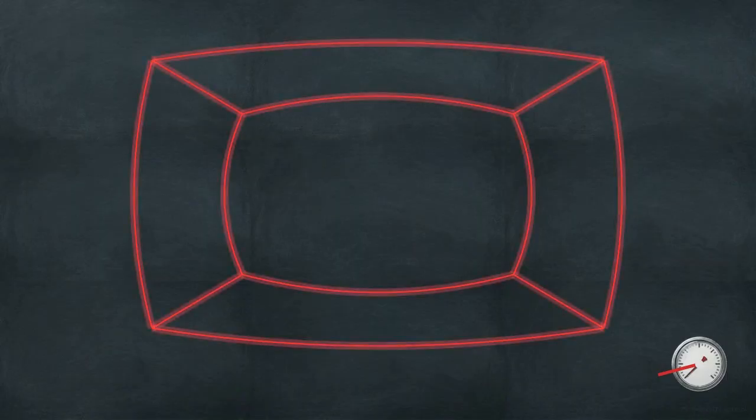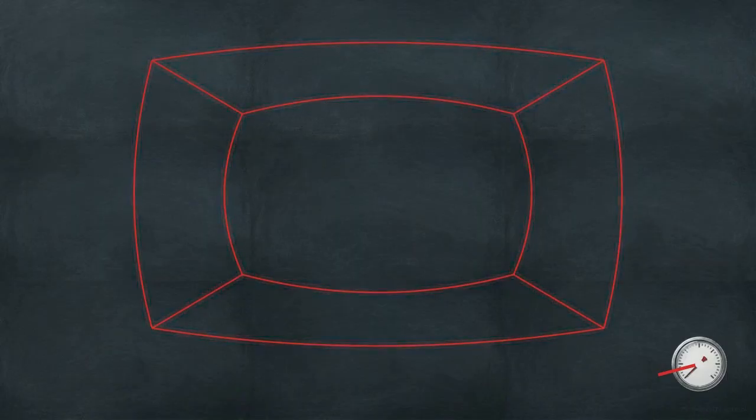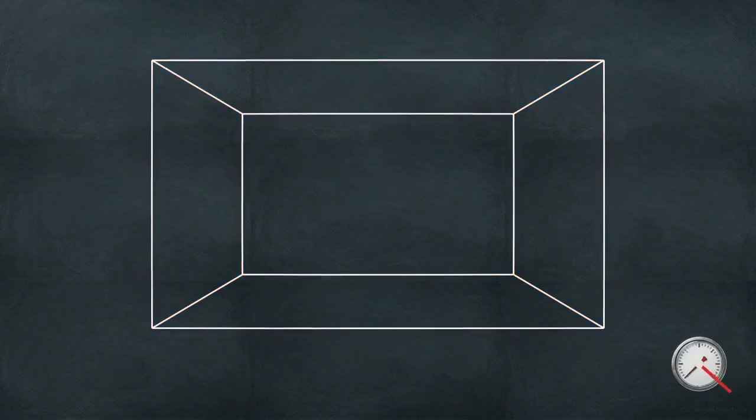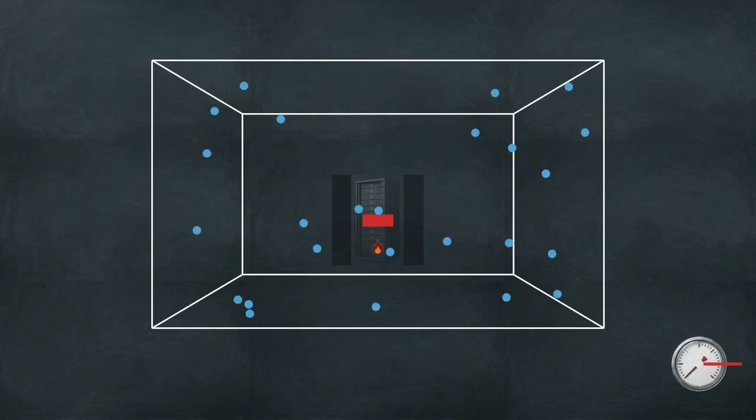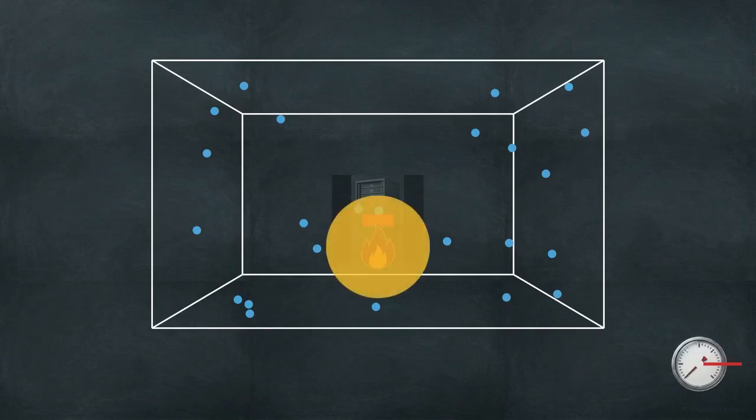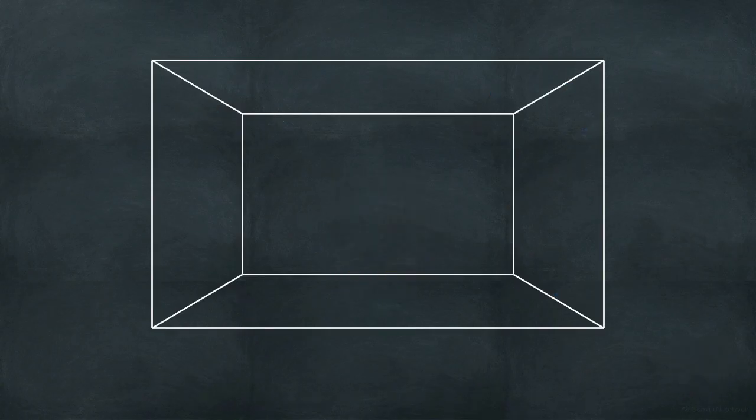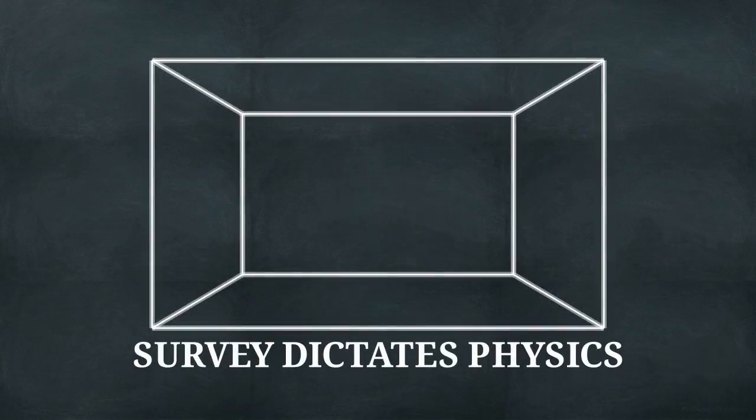An inaccurate net volume survey guarantees incorrect agent concentration calculations. If the volume is overcalculated by ignoring solid displacements, the system will deliver too much gas, generating excessive room pressure. If the volume is undercalculated by improperly deducting permeable server racks, the resulting gas concentration will be too lean to suppress a Class C fire. The accuracy of the physical survey dictates the success of the physics.